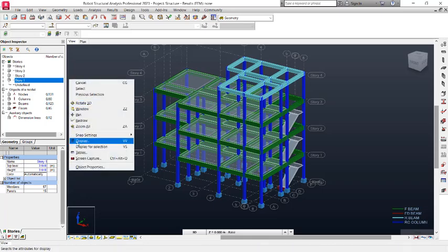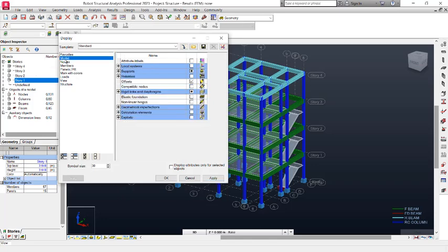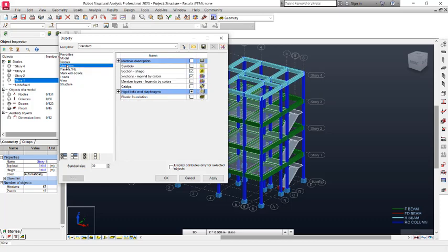Okay, select the stories provisions, and then you come to the model right there. So and then you check the model offset. You come to the members right here. The shape is already on. Click on that, apply that. So you will always be able to mark all of this by the color you want successfully.